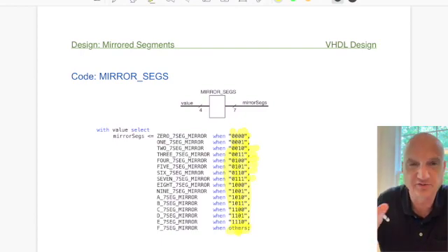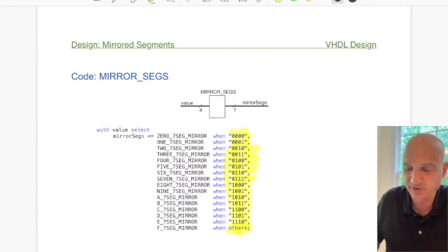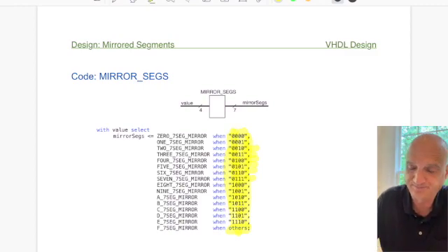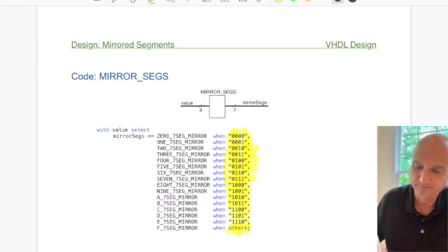We talked about the others clause before and how important that is to make sure this is combinational logic. Remember, we don't want any storage in here. There's no flip-flops. So we want to make sure that that happens by putting the others. But this is fine not specifying constants for because it's just a numerical sequence. The other exception to the rule is if you're initializing something to 0, for instance. That's fine as well. You don't need a constant for that.